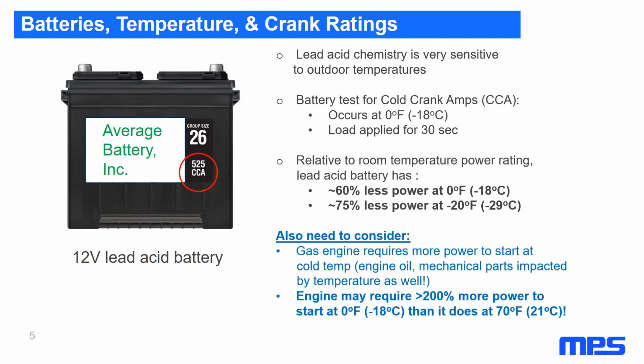It must also be considered that the vehicle's engine, including mechanical parts and engine oil, are also impacted by outdoor temperature. In a cold temperature condition, the engine will require more power to start. As an example, some engines require 200% or more power to start at 0 degrees Fahrenheit as compared to 70 degrees Fahrenheit.